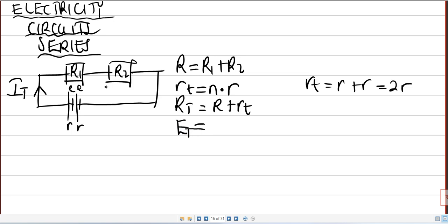So typically we say voltage in a series circuit would add. So for EMF, the first option for finding it is to deal with these 2 EMFs here because they're in series. Similar to how you found your internal resistance, you would say E total equals the first EMF plus the second EMF. Thus you have 2 EMFs. Alternatively, you may say number of cells times each EMF.